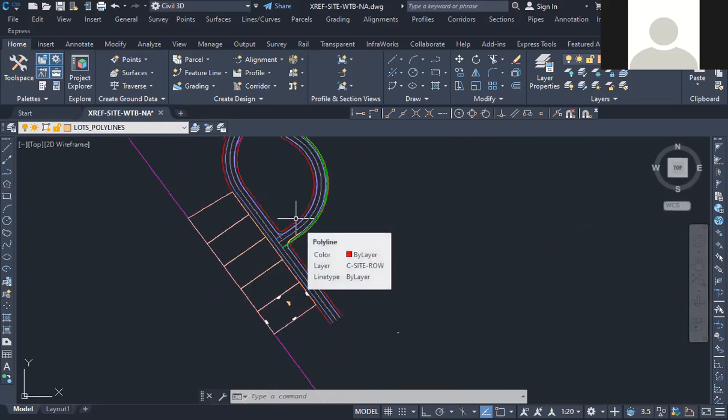So somewhere on the drawing, you're going to want to label all of your lots and you're going to want to label your road right of ways. So for this one, you see how it looks like a closed thing? For this road here, you're going to draw a line straight across, and that's going to be the area for this, and then from there up is going to be the area for the other. Does that make sense?